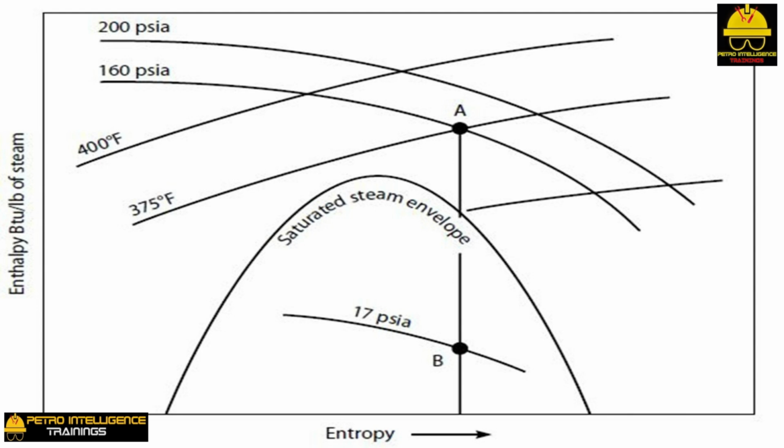6. Divide your answer by 2500 BTU per horsepower. This is the fraction of a horsepower that each pound of steam can produce. However, as turbines are not 100% efficient, multiply the calculated horsepower by 0.90 to account for internal turbine inefficiencies called windage losses. Incidentally, the reciprocal of the calculated horsepower per pound of steam is called the water rate, which is the pounds of motive steam needed to generate 1 horsepower worth of shaft work.